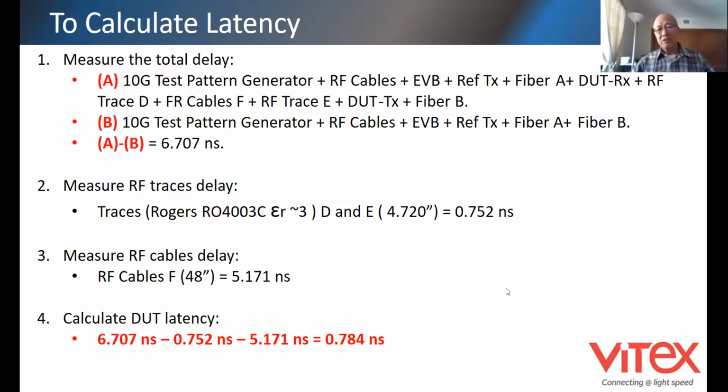Let me reply to you right now. So basically what you're talking about is to measure the rise time of the signal, not the jitter, right? The jitter, there are many lines. Rise time, if you do it correctly, you can do in the middle of the jitter, you can have your own rise time, and you measure that with the reference point, which is basically you can say 50% of the eye height at that point.